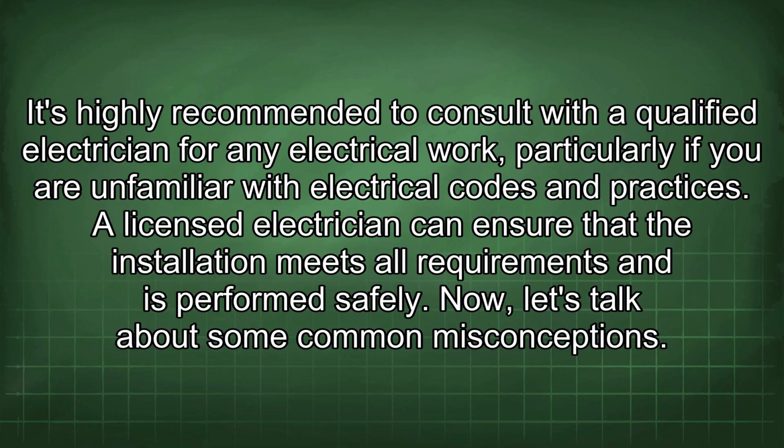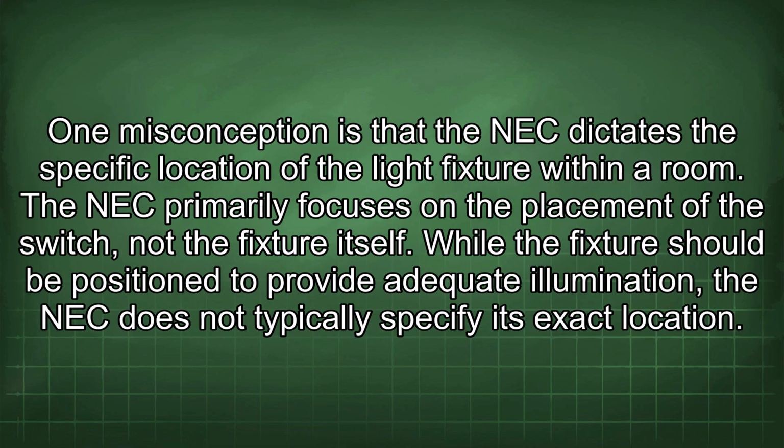Now let's talk about some common misconceptions. One misconception is that the NEC dictates the specific location of the light fixture within a room. The NEC primarily focuses on the placement of the switch, not the fixture itself. While the fixture should be positioned to provide adequate illumination, the NEC does not typically specify its exact location.